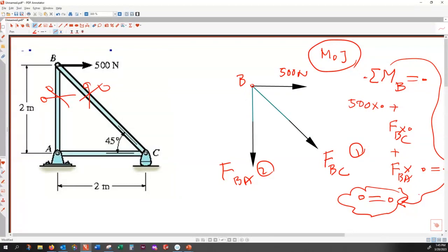Yes? No? All right. So therefore, Nguyen, that is my conclusion. If in a free body diagram, all forces are colliding at one single point, this free body diagram only has 2 useful equations, not 3 useful equations.